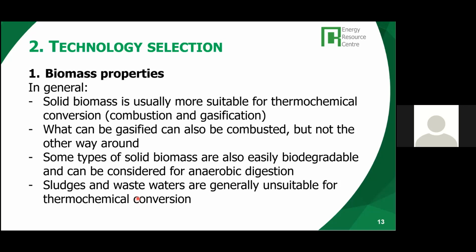whereas types of biomass containing large quantities of water, easily degradable types of biomass are more suitable for anaerobic digestion. We're usually looking at biomass in the form of, from water, which is very liquid, of course, to sludges, to materials that can have, let's say, up to 20 to 25-30% of dry matter. Let's say upwards from about 70% of water.